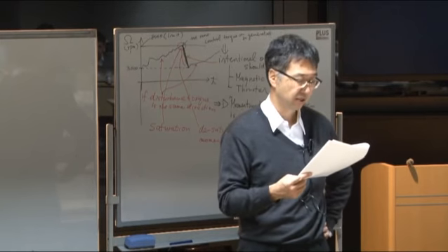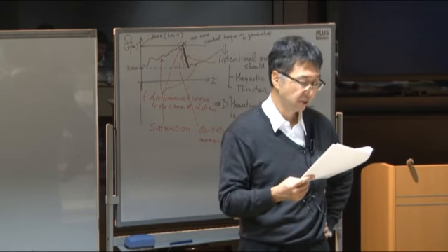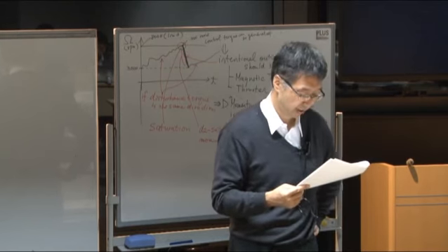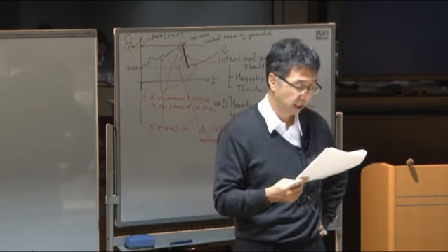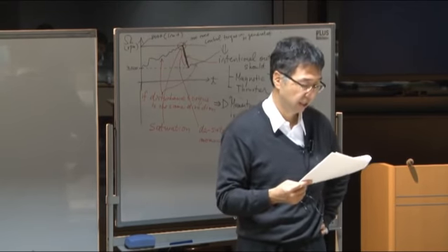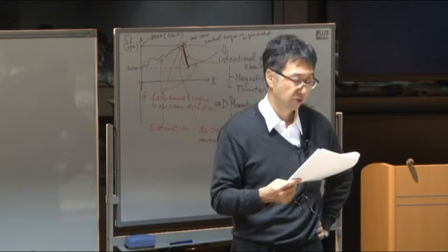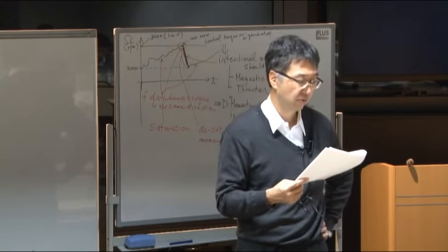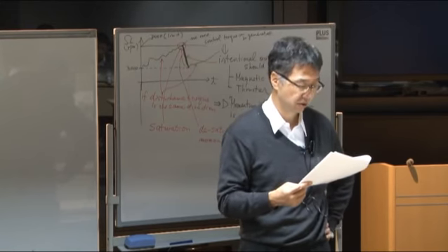Okay, 1,000, it crosses. So below this height, you should mainly care about the aerodynamic. And above this height, you should mainly care about the solar radiation pressure.